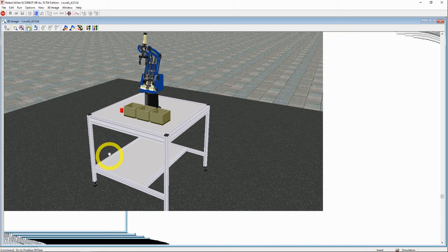Now that I hit run single cycle, you see my robot moves down here, position, and then picks up that cylinder. One thing you'll notice is in the previous activity, we calculated those different roll angles, right? Because we had a cube. We wanted to make sure that the gripper of our robot was actually parallel to the sides that it was picking up that cube.